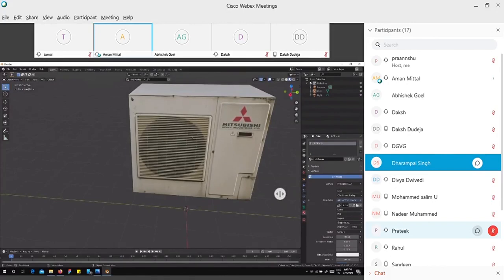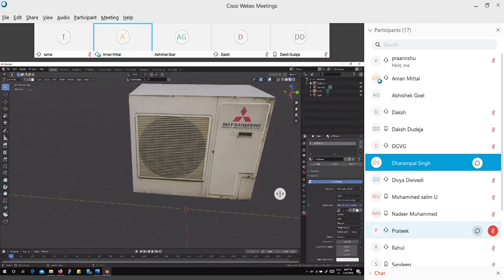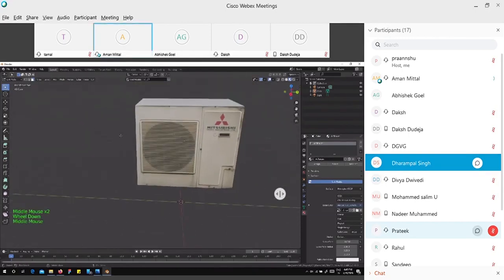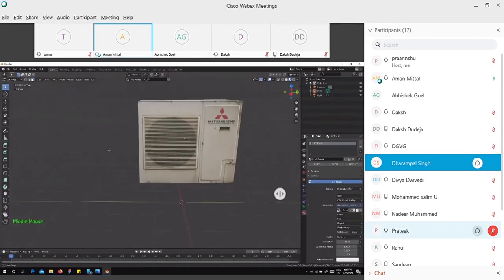By going to the edit mode. Edit mode is here. Just select the drop down, object mode, edit mode. Okay, now what will I do? I will add edge loops. Okay, so an edge loop is like a loop right here. You can press Control R or you can just select here.